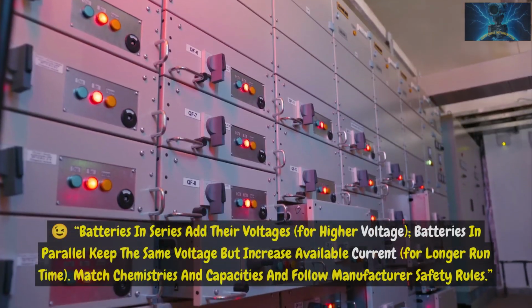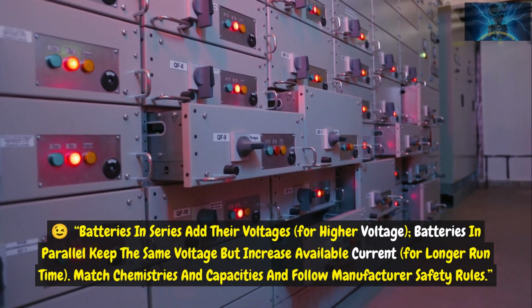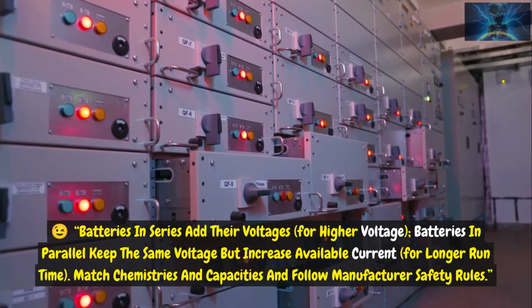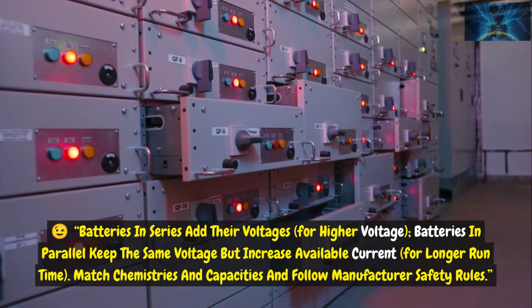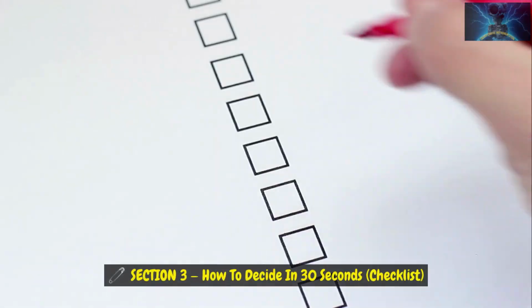Batteries. Batteries in series add their voltages for higher voltage. Batteries in parallel keep the same voltage but increase available current for longer runtime. Match chemistries and capacities and follow manufacturer safety rules.